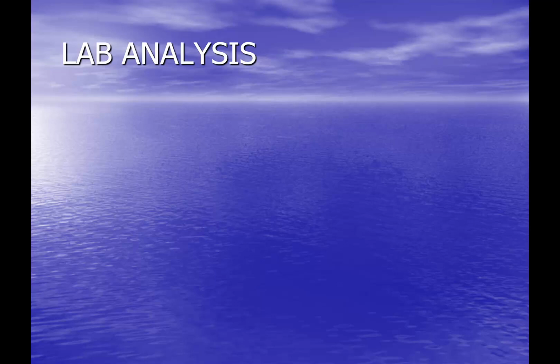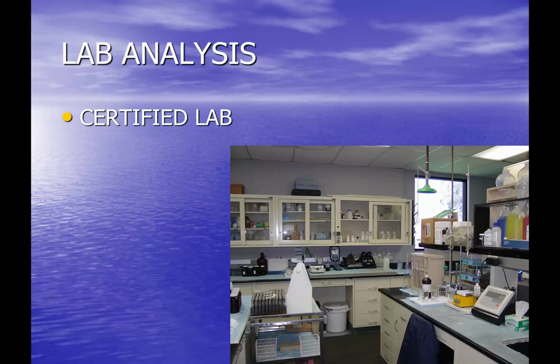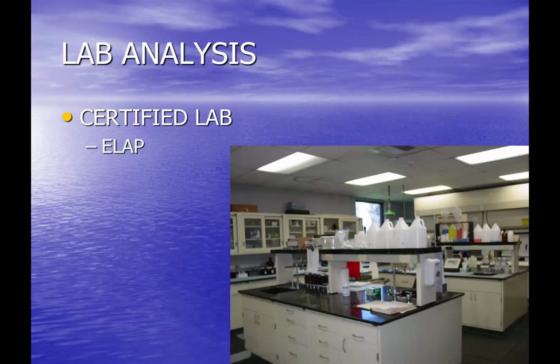The lab analysis itself is typically going to be done, or is going to be required to be done, by a certified lab. The El Toro Water District maintains a state certified lab. The certification program is called ELAP. So we are capable of doing all of our own bacteriological analysis. We can do all of the ammonia, nitrite, all that stuff as well. We outsource disinfection byproducts, but everything else we can do ourselves, as well as all the wastewater analysis that we do to make sure that the plant is operating properly.